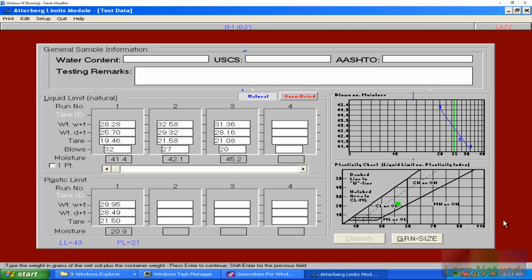So let me give you the general synopsis of classifying samples. If you were to classify a soil, let me step back a bit. There are 2 ways that you can. You can do visual descriptions and classification visually, which takes years of experience handling the material and stratifying material, which is a fancy word for just examining the strata of the soil. That's what I call stratification. So all the different layers and stuff.